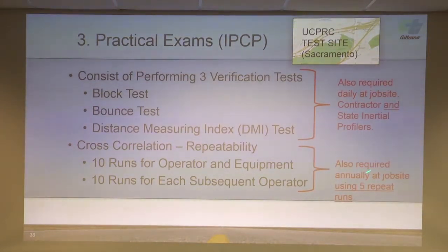Then the specs also call for a cross correlation test one time on the project per year, where they'll run through it 5 times. But daily, I can't stress this enough, we've got to make sure that our inertial profiler operators are doing this DMI test every single day.